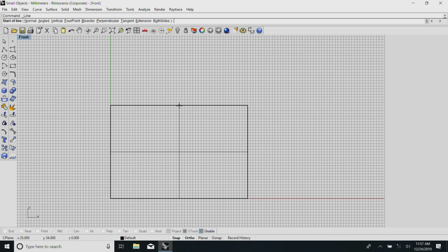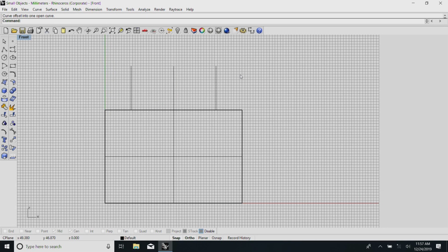I have typically the center line, and I need to offset it by 15.5 millimeters on one side and another 15.5 millimeters on the other side, for a total of 31. Now, I need to make a depth of 11 millimeters. So, easiest thing for me will be to join these two ends.